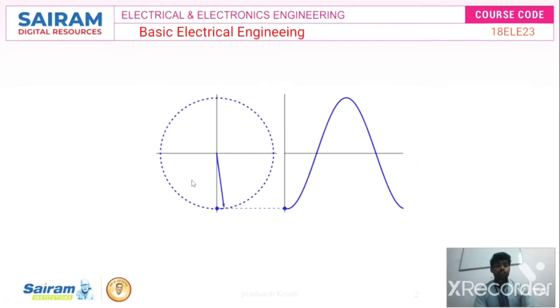This is one logic, that's why I have not given the heading, because we have to assume what this is. This is the generation of single phase AC voltage, or generation of a sine wave, right? The complete rotation gives us one sine wave, a positive half cycle and a negative half cycle. The conductor moving from here to here is the positive cycle. If it is from here to here, you will get the negative half cycle. The same thing comes from the power plant to your home.